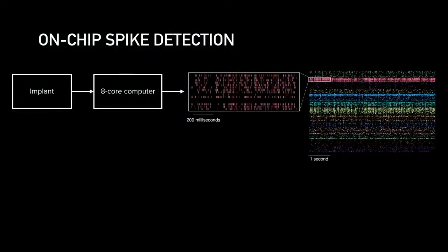Our analog pixel can capture the entire neural signals sampled at 20,000 samples per second with 10 bits of resolution, resulting in over 200 megabits per second of neural data for each 1,024 channels that we record. In our previous systems that you heard about, we were able to stream this entire broadband signal through a single USB-C connector and cable, and we performed real-time spike detection on an 8-core machine running our optimized C code.